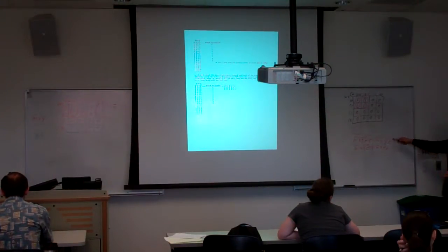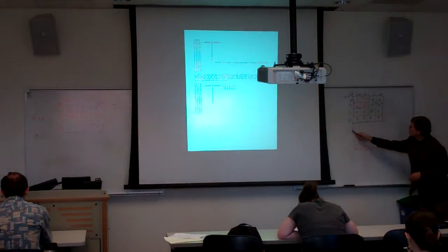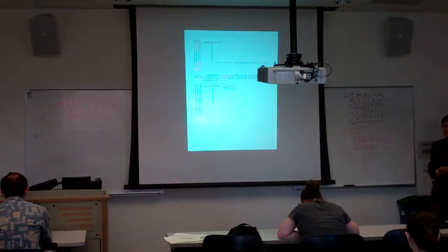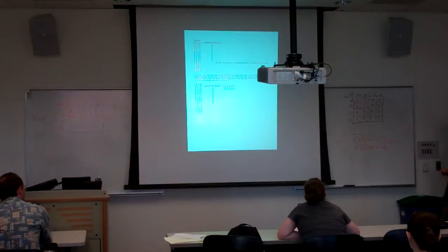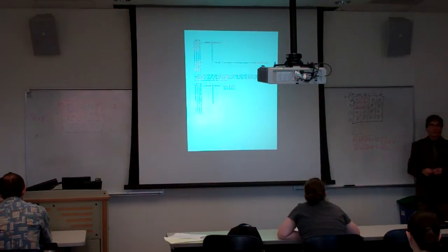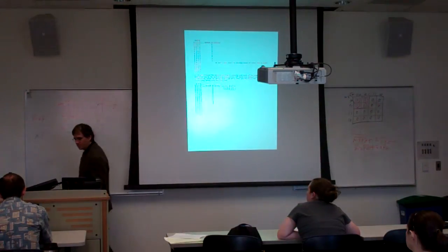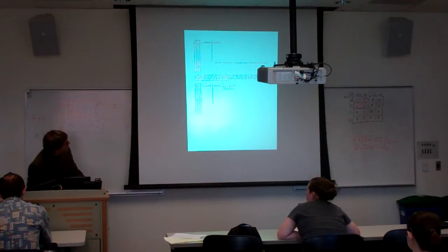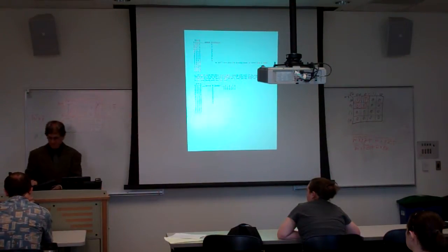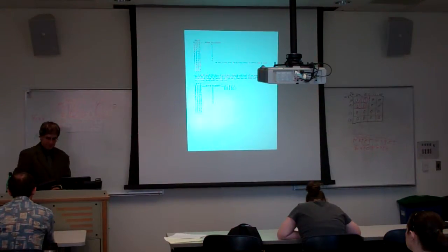Okay, so you can get that from there, but the more coverings you do with your rectangles, the smaller your solution. This is going to take a single AND gate to implement. This is going to take 4 AND gates, each with 4 inputs, and it's going to take a 4 input OR gate. So it's a lot more transistors. Okay, it's also going to be slower because you're going to have 2 levels of logic. You're going to have a series of ANDs, and then you're going to have an OR. Whereas a minimal solution is just 1 gate, so less propagation delay.